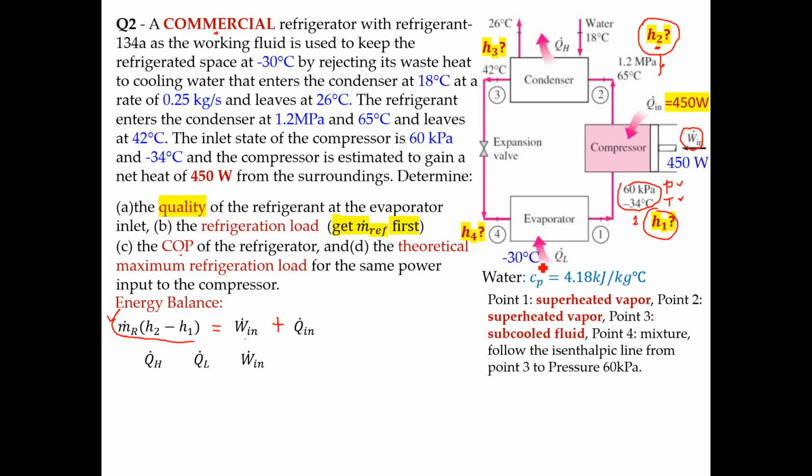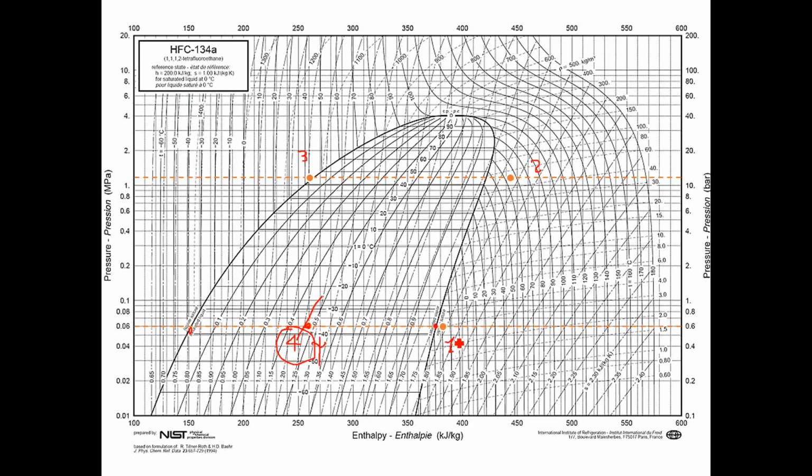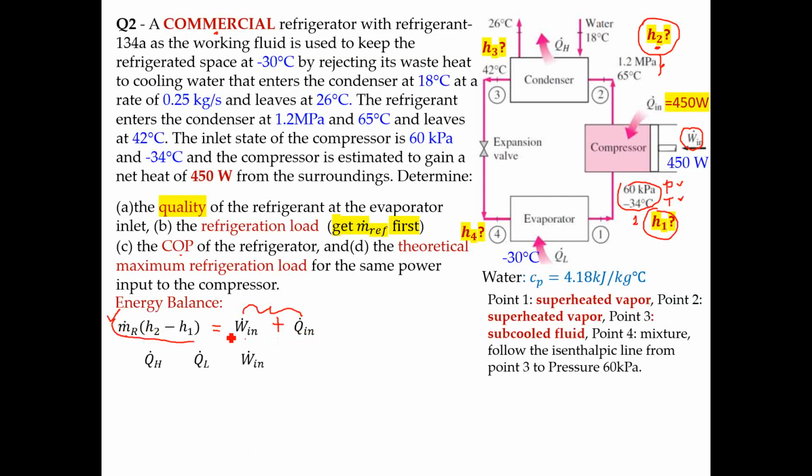So that basically means we have the work input to the compressor, and meanwhile the compressor is emitting heat. So both of these amounts of energy will contribute to the energy change between point 1 and point 2. So you will see that h2 and h1, which you read from this table, actually give you the information of both. So when you are looking for the COP value, you will need this one only. So that means, as we said, you can calculate this easily.